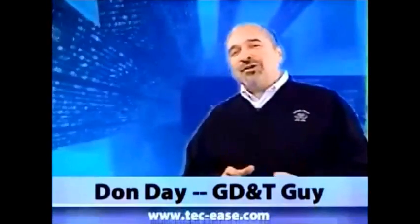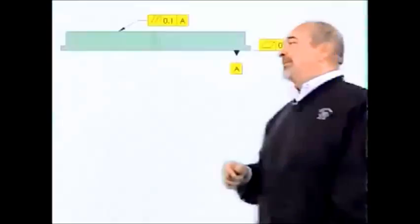One more time. It's the datum, not the datum feature. I must get a question on this at least once a month. This time the question was, how can the datum be bowed and have a parallelism on a planar surface relative to it? Well, it can't. Before I show you the drawing, let me say that I didn't use good practice on the drawing, but I wanted to make a point.